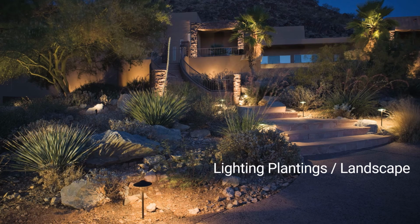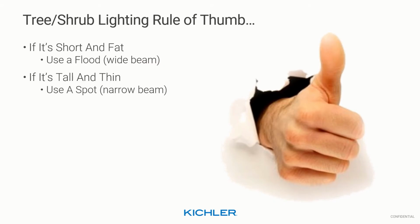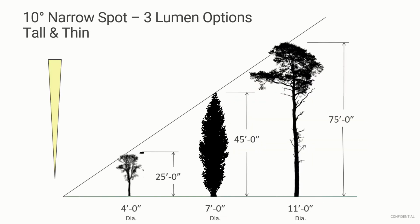Now we'll touch on the lighting of plants and trees. A quick rule of thumb to always remember: if the tree or shrub is short and fat, use a wide flood or wide beam light. If the tree is tall and thin, use a spot. This selection of narrow, tall trees are best lit with narrow beam lights. Remember, as the trees get taller, higher lumen levels will be required to reach the top.